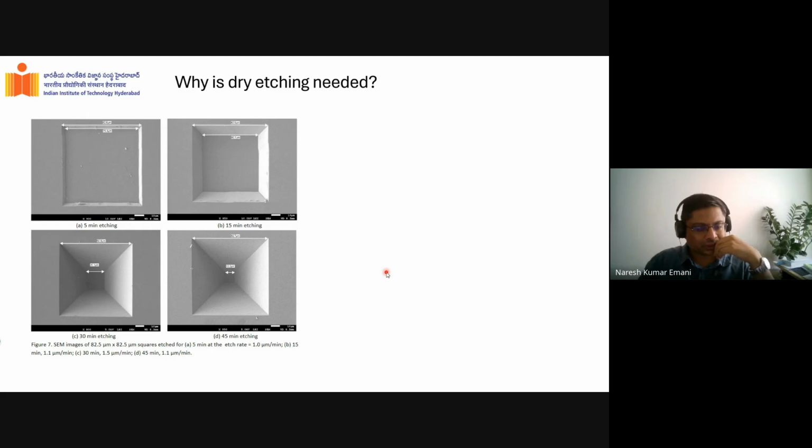Okay, fine, good. So he must have shown you some structures like this. What you are seeing on this slide are some images of silicon. After different etch times, you have some shape which is etched into silicon. Is this etch isotropic or anisotropic? Anisotropic, right? So we are able to fabricate some features like this, and they're quite anisotropic.